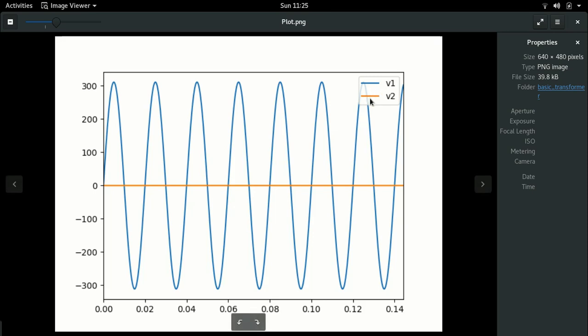But winding 2, which is the secondary winding, is 0. That should not be the case. It should also be around 340 because we have a 1:1 transformer. So this result is obviously wrong, right? Now what could be wrong?